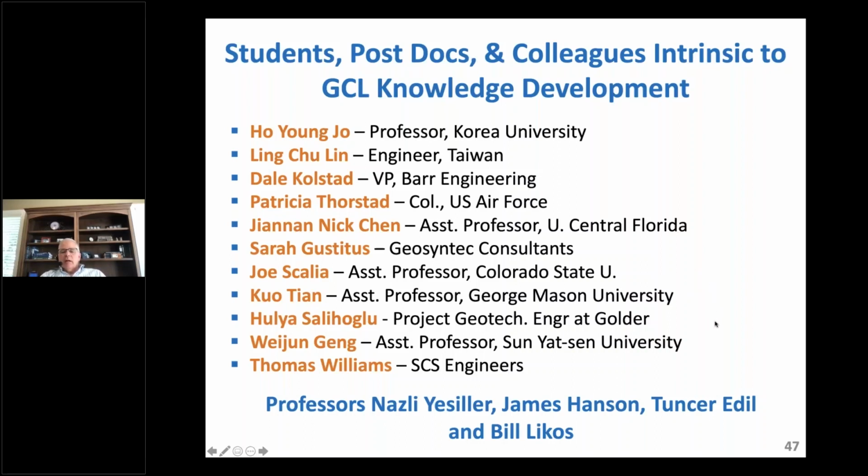Jimmy's from Solmax, a good friend of mine and colleague. Could a coated GCL be used to protect from ions underneath the GCL? Certainly can. It's a great example. And I wish I would have thought of this earlier, and I wasn't thinking about it in the previous question. But a coated GCL is the same as a laminated GCL. It's just a different type of laminate, right? And in this case, you're just flipping it upside down and putting the laminate at the bottom as opposed to at the top in the cover. But yeah, that laminate or that coating is going to provide that protection.